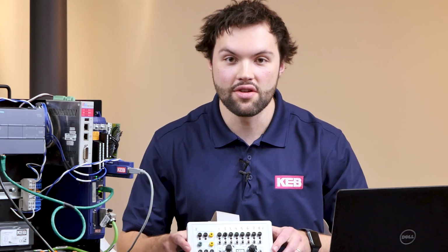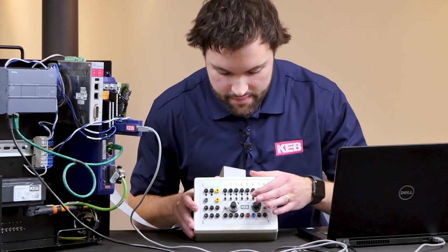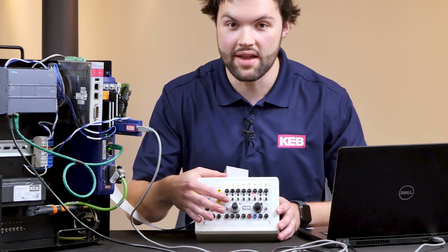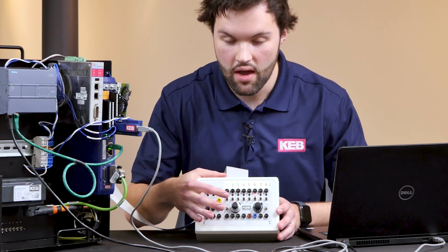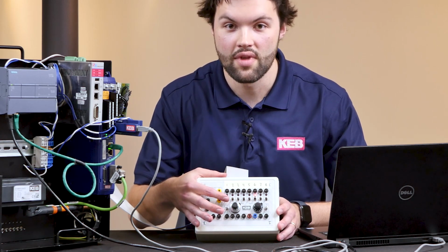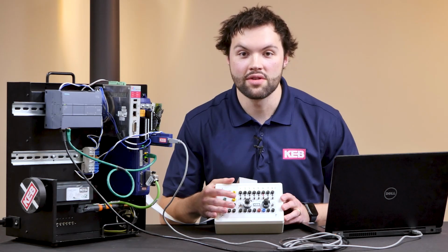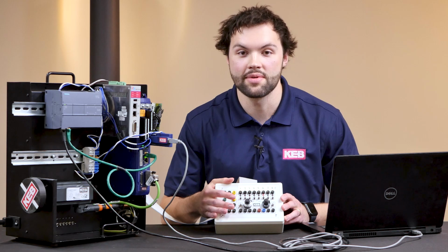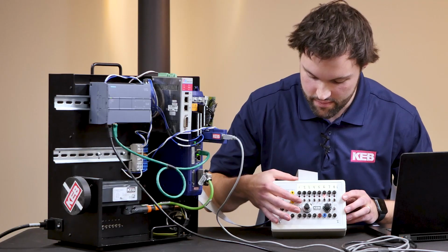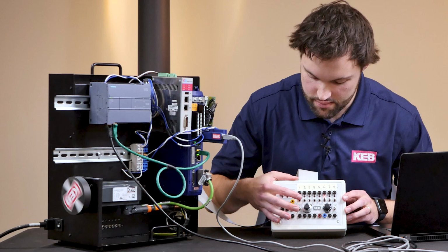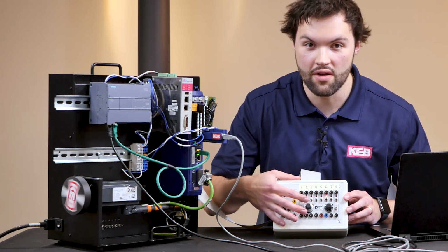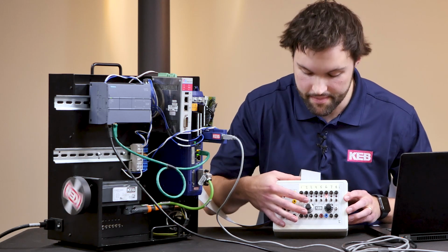To activate profile positioning mode, simply give digital input 6 a high command, and we'll start at state 1, state 2, and our enable operation state, state 6. As we go into state 6, the motor will spin the opposite direction since I set a set position in the opposite direction. And then to stop, I'll give digital input 2 a high command.